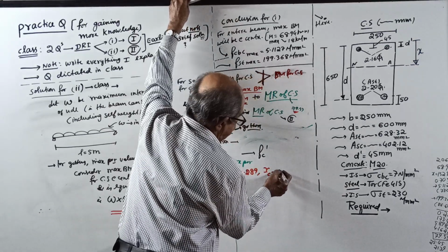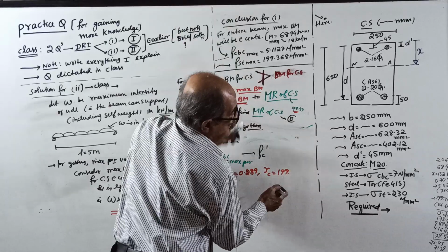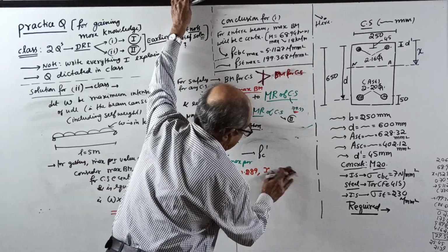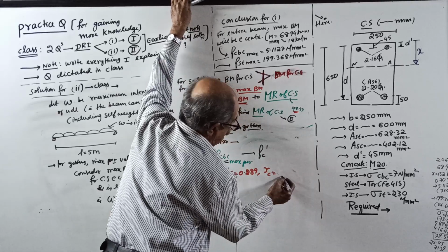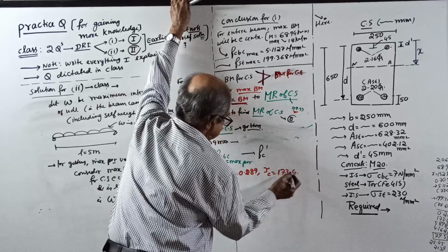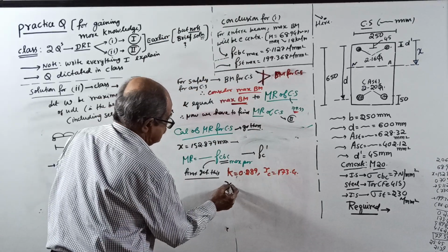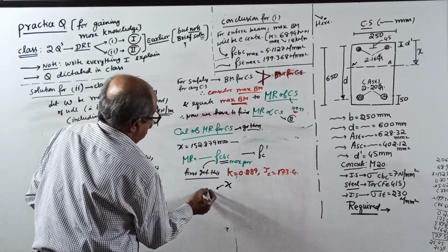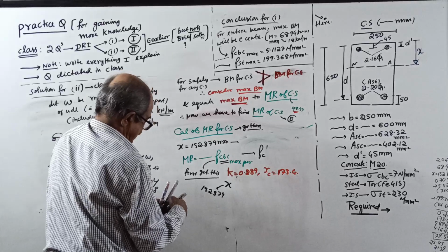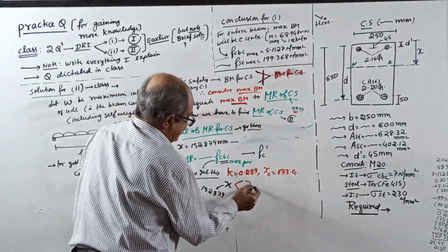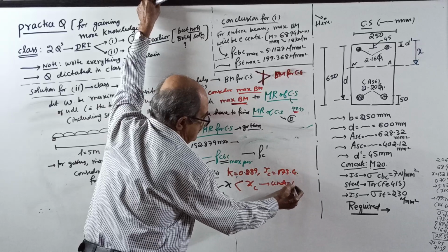It is somewhere 199.368. I doubt. No, I can make out it's wrong. Some other number. It is 173.4. Your X, which you got, how much? 152.879 millimeter is less than XC. The cross section becomes an under reinforced section.